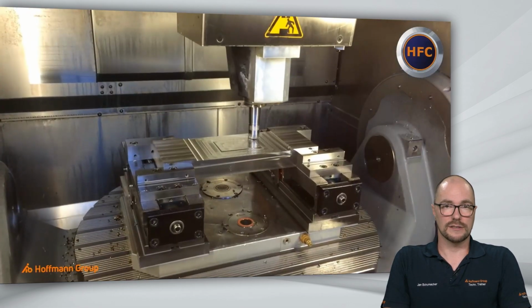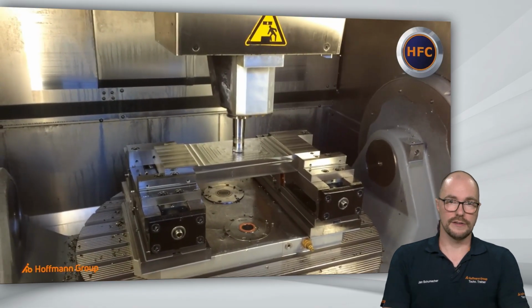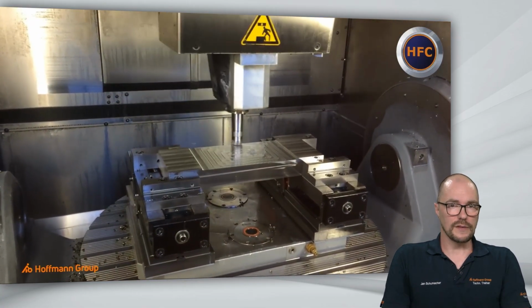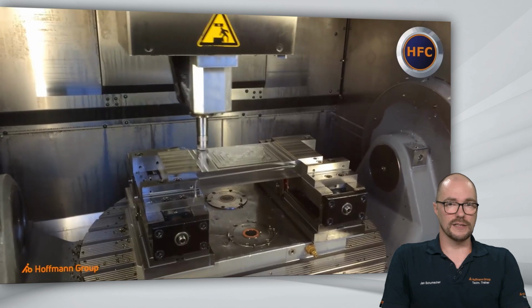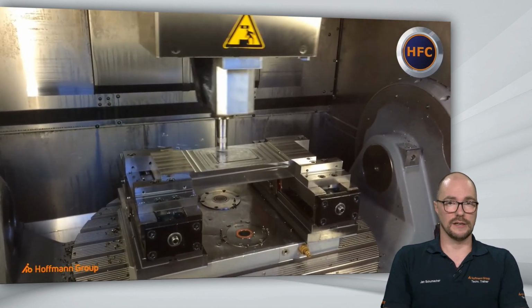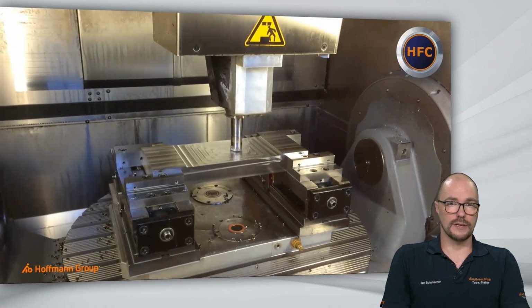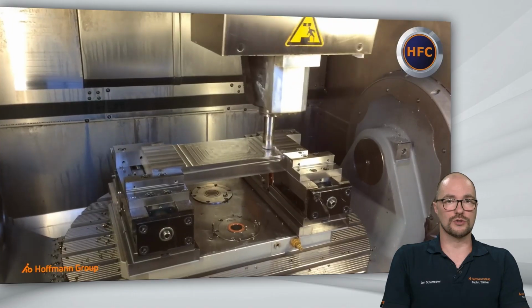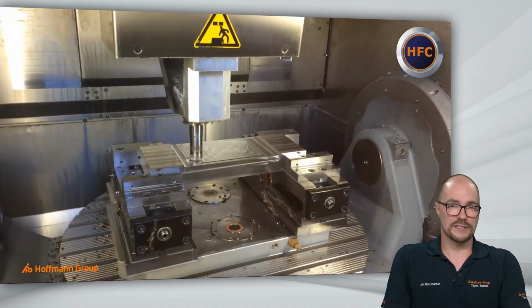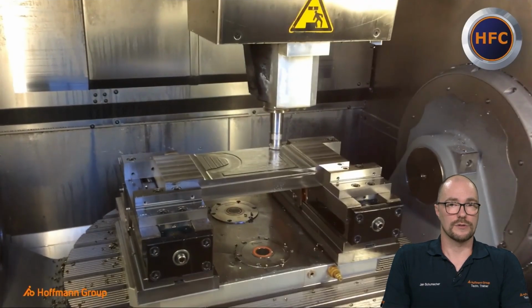Let's have a look at a nice video once more. You can see a high feed cutter, which is rather long. It is equipped with 5 cutting edges. It is a modular tool, and each of those cutting edges is driving the tool 2 millimeters per rev. So in sum, this tool drives 10 millimeters per revolution, and that's where the insane speed comes from.